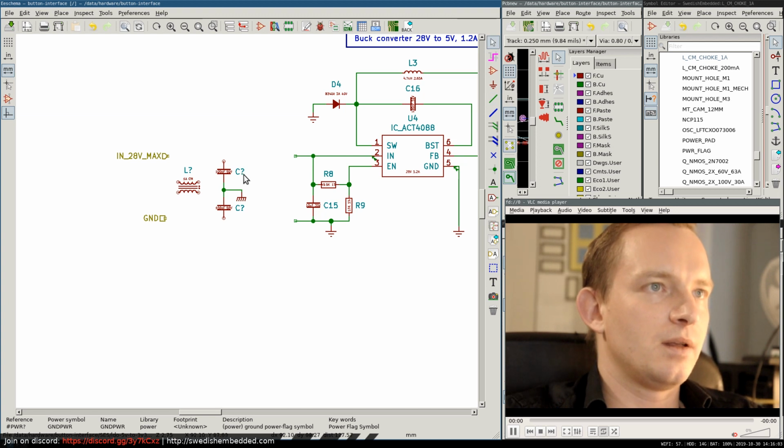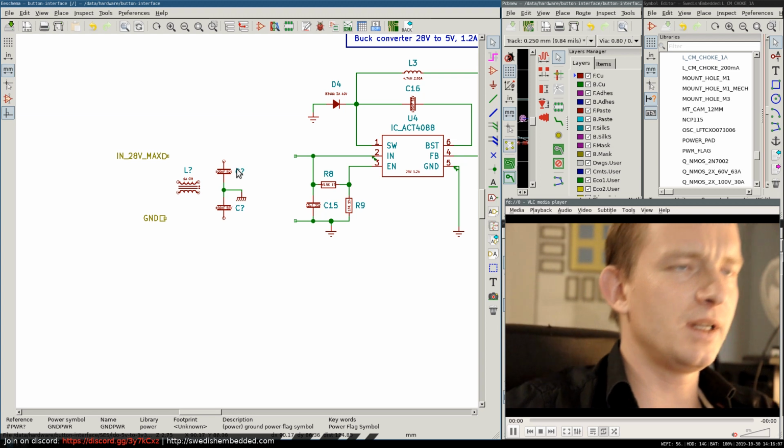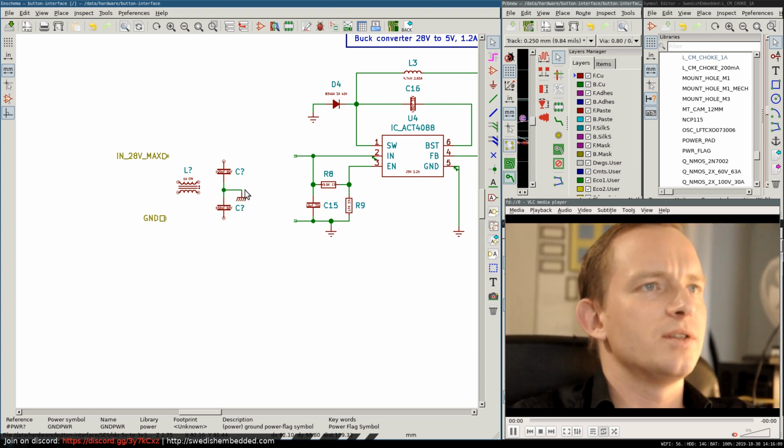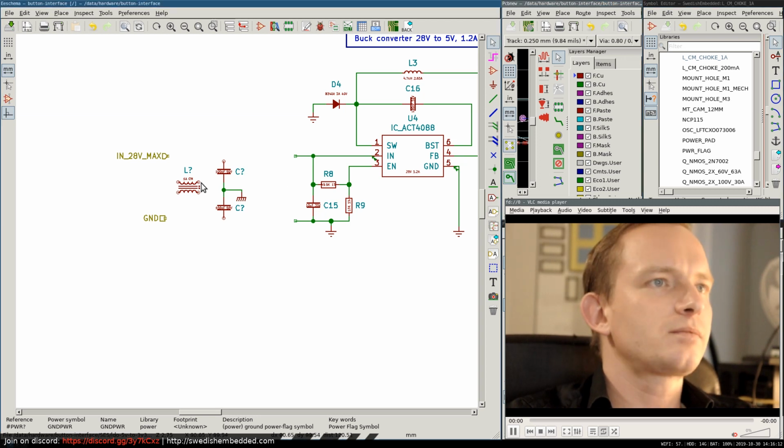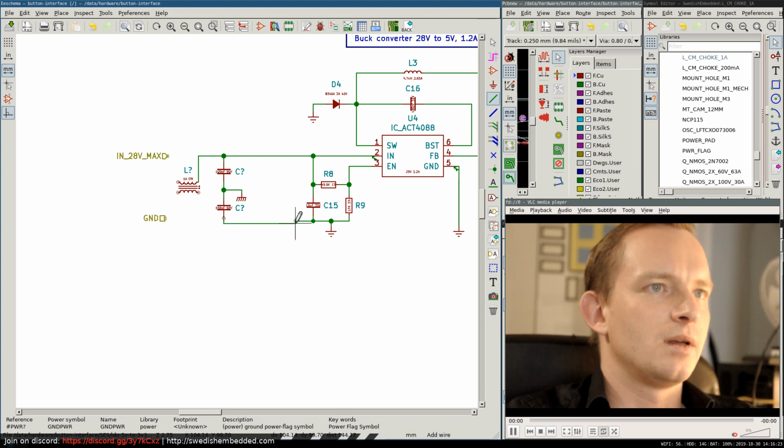Now, the mounting holes are not going to be connected to the ground. And we can either make the mounting holes non-plated holes or connect them to the chassis ground. So if we make it this way, let's say we do like this. So this would be a common mode line filter.